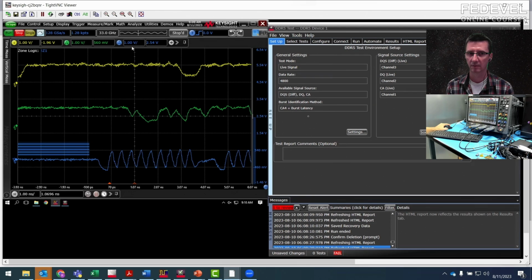Robert, I want to point out something kind of important. This signal is really noisy. See the noise on top? We're measuring DDR5 4800, and remember, I said 4800 megabits per second. The fifth harmonic is about 12 gigahertz. For that speed, that would be the average bandwidth I want to use. Typically it's more like 16 gigahertz, but 12 is the minimum.